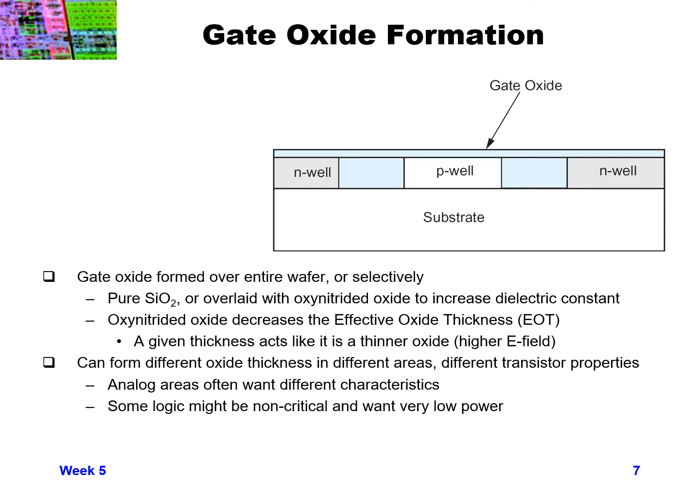Keep in mind, gate oxide, silicon gate, you expect the gate to have no current through the gate, but as you get to thinner and thinner oxide, you actually start getting some tunneling current through the gates. So this allows you to get less of that tunneling current through your capacitive gate, because you expect capacitors to have no DC currents. And so this allows you to reduce that parasitic tunneling current that you would otherwise get, and get a better electric field for a given thickness.